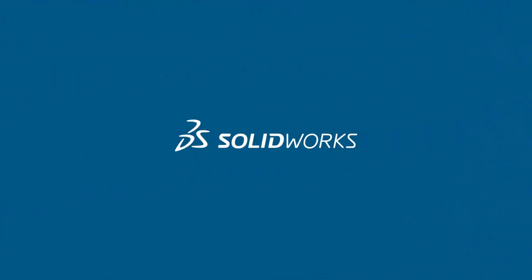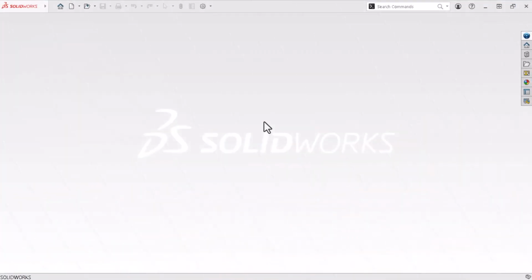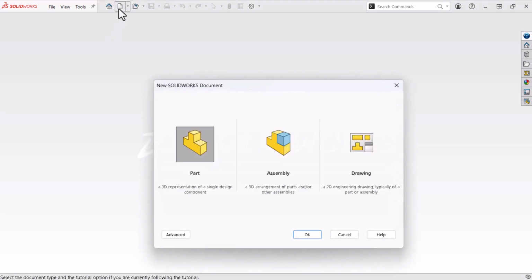Let's get started. I have SOLIDWORKS open, which I'll use to save my data to the 3D Experience platform. I'll start by expanding the menu bar pull-downs at the top and clicking the pin icon to keep it visible. Now, I'll start a part. To do this, I'll click New at the top of the screen. The new SOLIDWORKS document window opens.